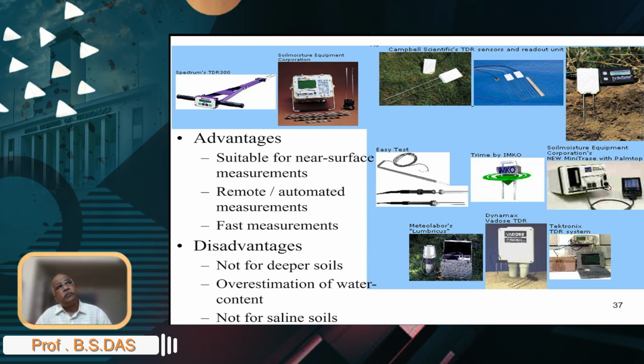The frequencies operating in these TDR probes are at about 3 to 16 gigahertz range, because that's where these differences in soil textures go away, and so you can just use a single calibration curve, just like a factory installed calibration curve. Measurements are fast because of the electrical nature.